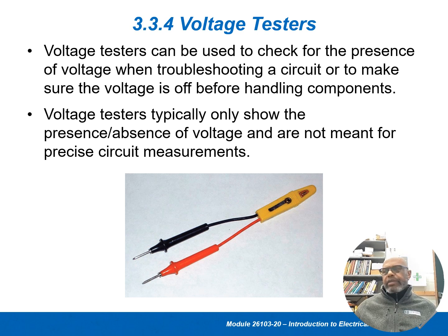Now, this is a voltage checker. It's inexpensive. Basically, it's not for continuity. This is actually for reading voltage to see if there's voltage. It's, like I say, very inexpensive. So if you cannot afford a meter at this point, you just need to know if there's voltage there or not. This device, basically, you put it on both sides of the power, and there's a little light that would glow. It's powered up from your power source. When it's low voltage, it'll be dim. When it's high voltage, it'll be bright. So again, this is a simple way. Some guys made their own by using just a light bulb with clips on it. If it glows, it's good to go. If it doesn't, they know it's an open circuit.